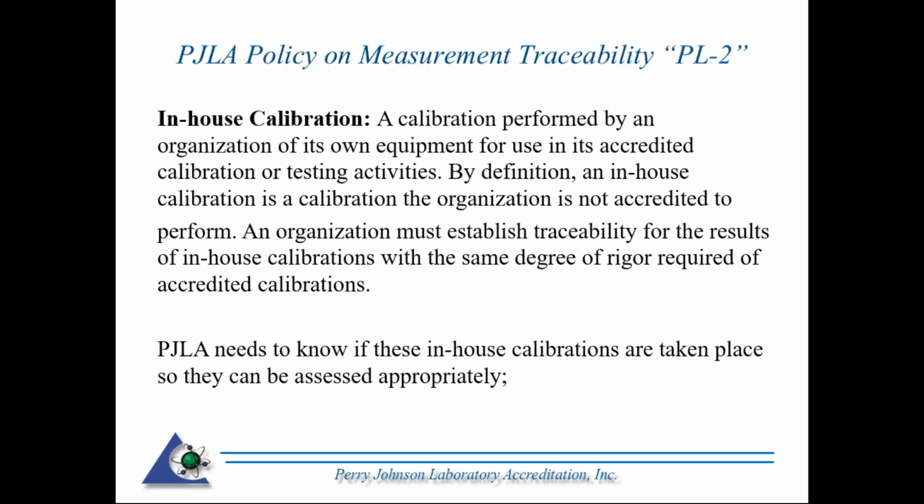So, in other words, if you are calibrating your own standards, let's say, for example, you have a pH meter and you have buffer solutions that are traceable, and you are going to do those calibrations in-house instead of sending them out. If you have balances and you decide for whatever reason, hey, we're going to calibrate our own balances. What an in-house calibration basically is stating here is that it's going to be the same as an accredited type calibration, except there's something that's not published on your scope. So as far as things like measurement, traceability, competence, uncertainties, all those things will come into play for in-house calibrations.